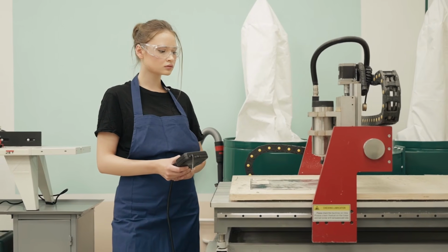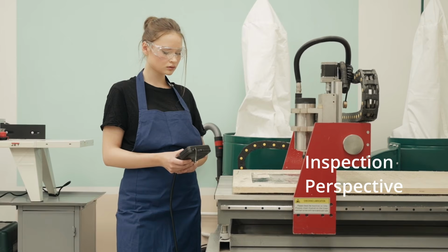And the third perspective is the inspection perspective. As a designer, we have to also think as a quality inspector. Like after manufacturing, how do we want our part to be inspected? How the parts should be set up for the inspection, what will be the inspection sequence, and we can define all those things only with the GD&T. Also, we have to keep in mind what are the inspection tools we have in our inspection room. We cannot define any such tolerance or control which cannot be measured accurately. Otherwise, we will end up with no inspection or high cost inspection, and we don't want it.